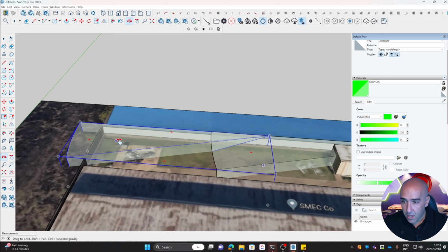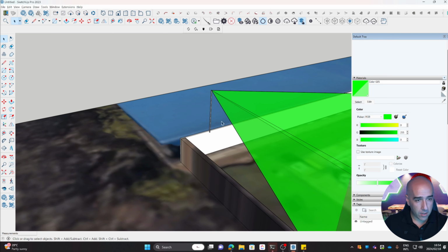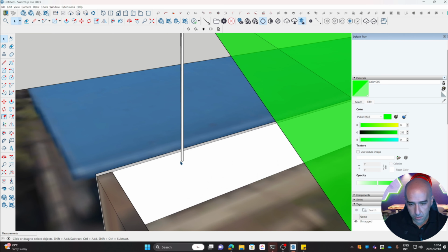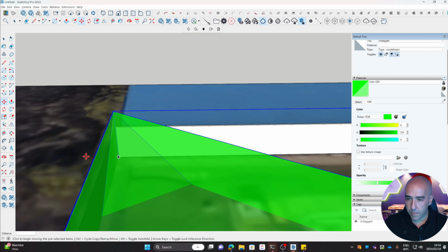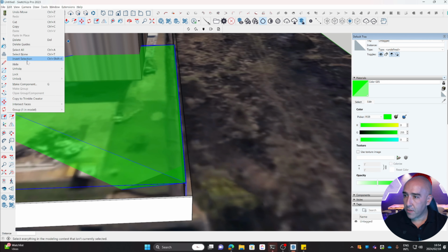We now put a color view camera over here. Okay, you might find that you can't get it down there because we've got the previous camera's view. So just click it so we can drop it. Let's click on the previous view, right click, and just say hide. Okay, so now we can carry on working. Let's grab the bottom of this pole again. Click, zoom out. Now we can go to edit, top left, go to unhide and press all or last. Follow the order that you've hidden things. So I'm just going to say all.